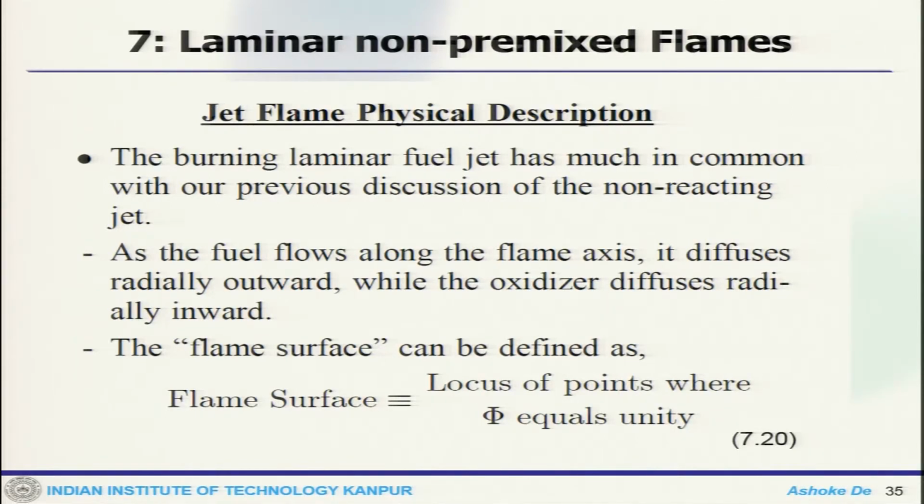Now, once we do this, we can look at the jet flame behavior. So, now the burning laminar fuel jet is quite similar to the discussion that we have done for the non-reacting jet. And to get into this burning jet, we have first looked at how the jet flows look like, how the central line velocity profile changes, and all these characteristics.